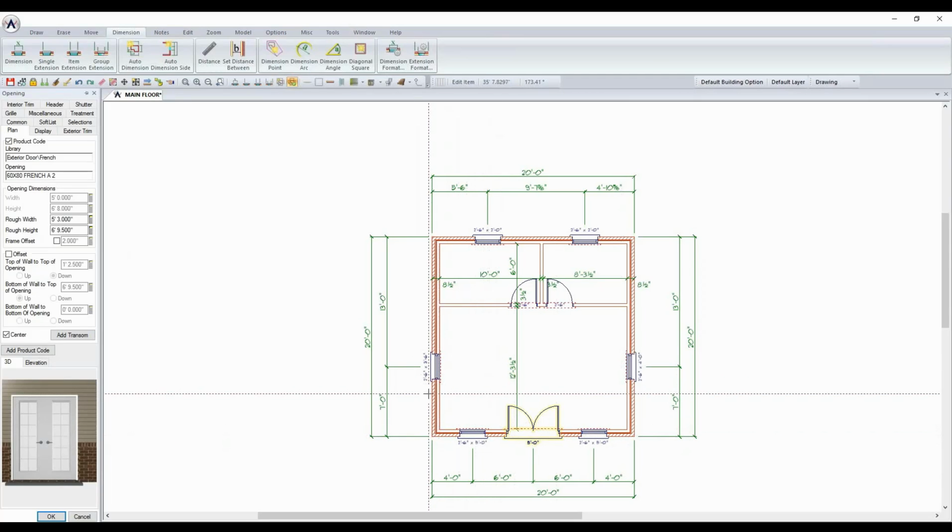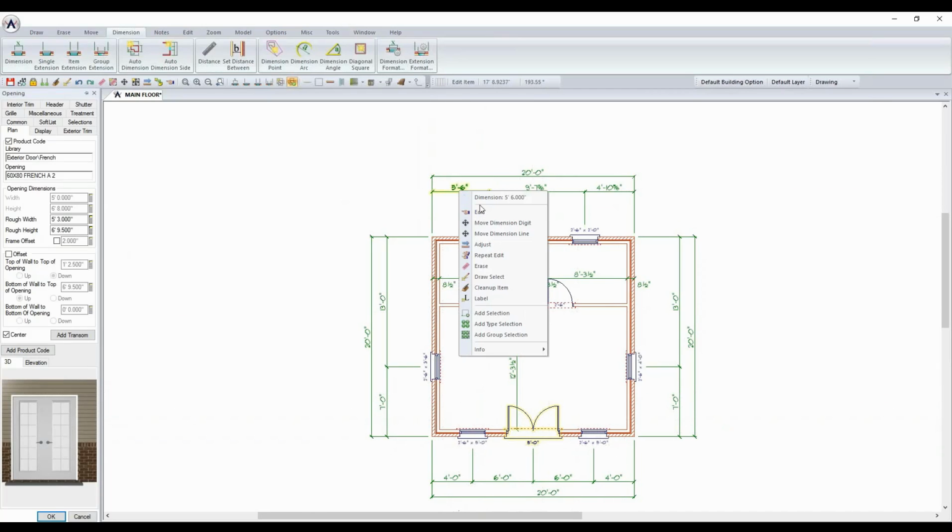If there are other walls in there, when you're centering openings across a wall or equally spacing them, it wants to know where they're referencing, inside or outside. In this case, there were no concerns because the outsides of the walls would be the same as centering it between the insides of the walls, and it will center it up. And you can see that by looking at the dimensions that they are set.